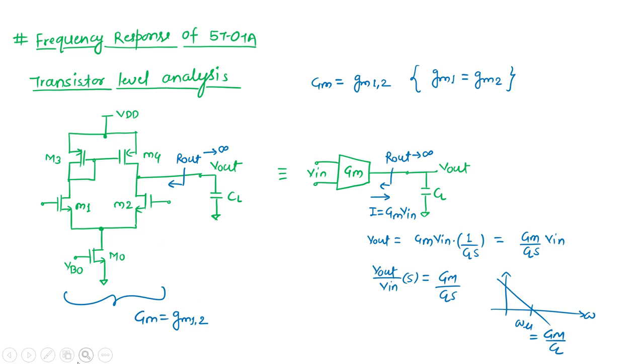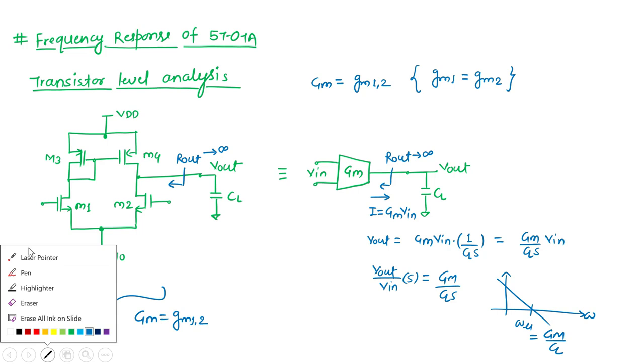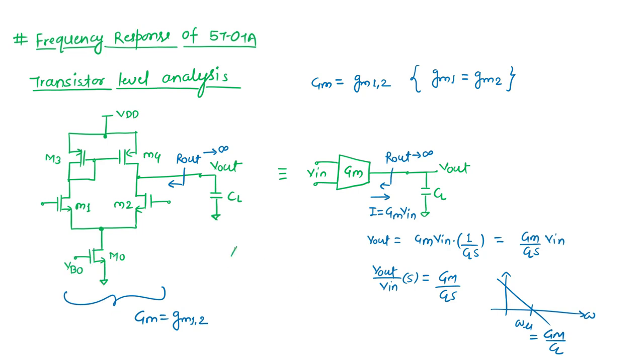This is our target, we have seen many times. So what is the target? Target is our gain to be infinite. It is not the actual target, but yeah, it is an ideal behavior of this op amp. For the ideal case, the error is 0. This we have seen already, and closed loop gain was coming out to be 1 upon beta, where we have seen these things in detail.